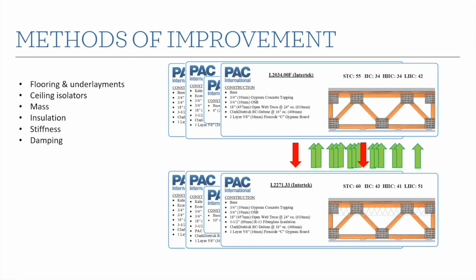And we can add damping to structures in different ways. There's damped gypsum board panels, and there's other ways of adding damping, and there's probably some folks on here that get into really crazy tuned mass damper systems for high rises and things like that. So that can be a complicated subject, but just know that it's there as a tool sometimes.